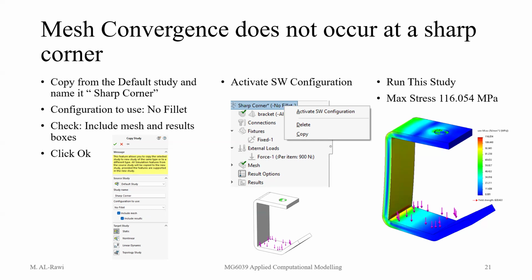And then add, right click on external loads, forces, select that to add 900 newtons. Are you there or did you get lost? So you start with the static study, and now you select the, so we're repeating what we've been doing earlier. Then apply and close, and then you come to fixture, fix geometry, select that face, and then external loads, forces, you select that one, type the value 900, and then click accept. So we've kind of replicated it.